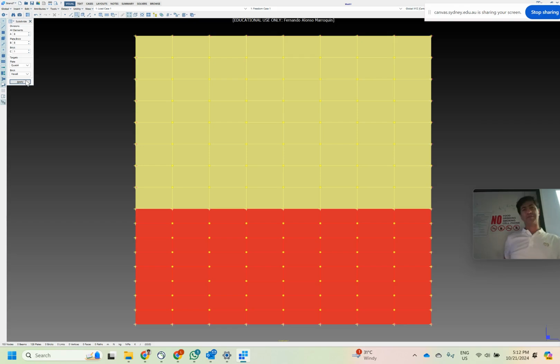Yes, here there is one detail. For finite element analysis, you want to make the elements as square as possible, because the error in the finite element solutions increases when the elements are distorted. You see that this element is not very square, especially the top elements.